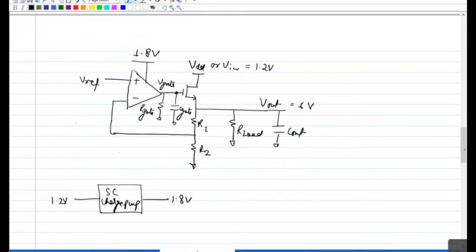Sir, I have a question. When the dropout voltage is large, say it's greater than 2V overdrive plus VTH, in that kind of scenario, is there a metric to select whether I go for a switching regulator or an NMOS linear regulator? Or rather, efficiency wise, if the dropout is large, is this a good choice? No, it's not a good choice.